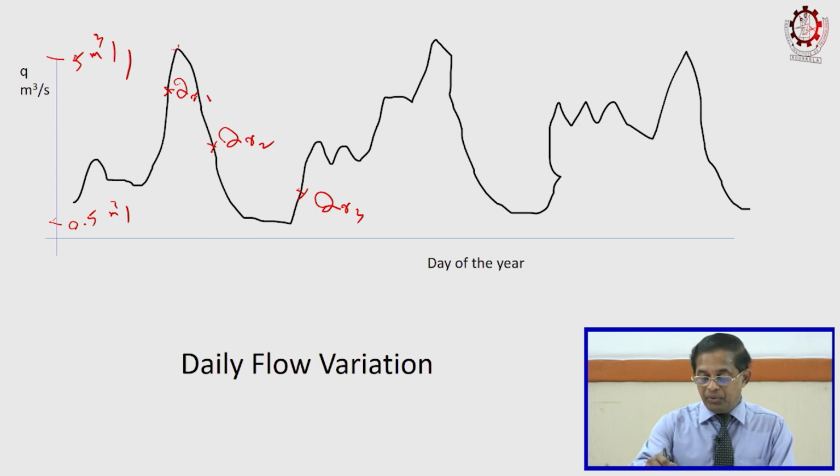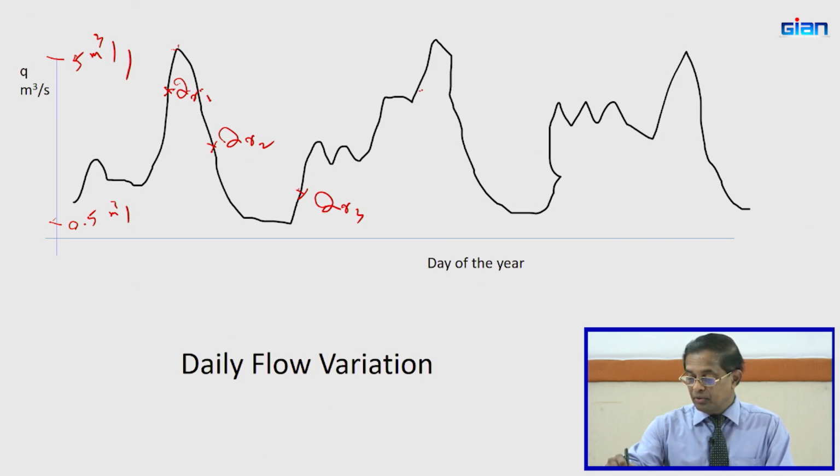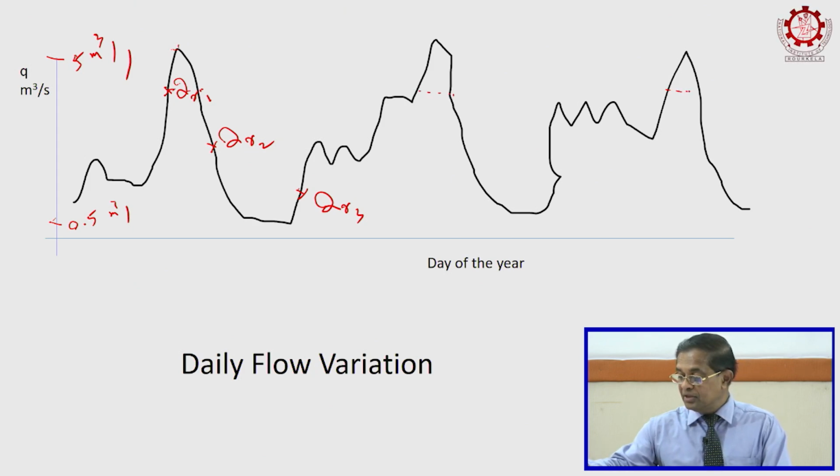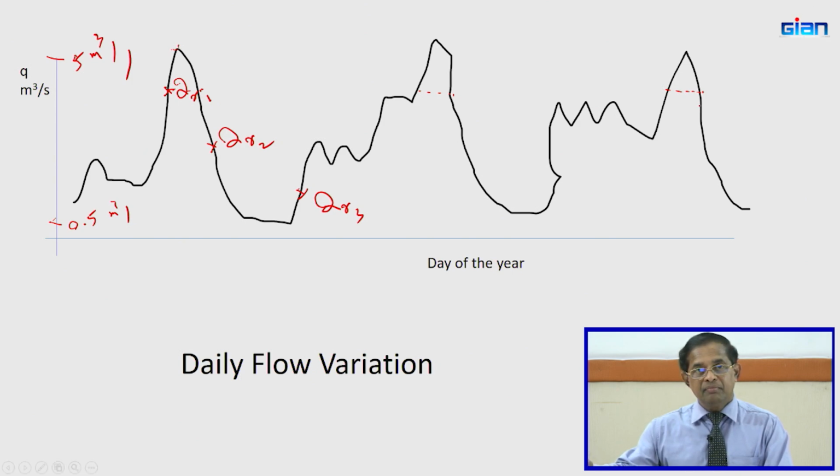If we use QR1, which is a high value only during this period, your plant can run on full load only during those small periods, because rated flow is available only then. And if you select QR2, you can run a longer time at the rated capacity.